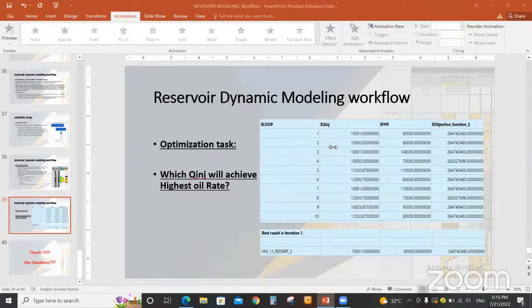That is the objective of normalization. But nowadays we can have a capillary pressure curve and relative permeability for each zone, for each cell, but it will lead to higher time running the simulation. So you have the two options.